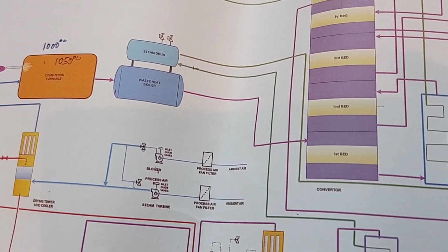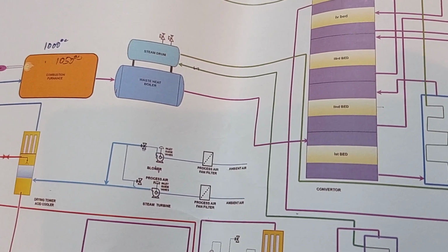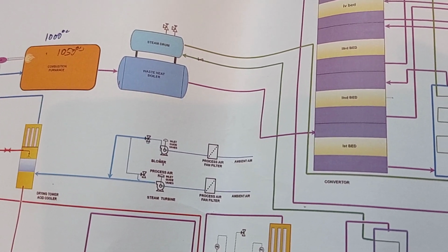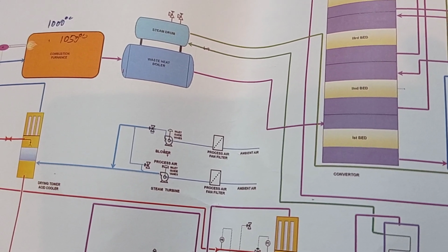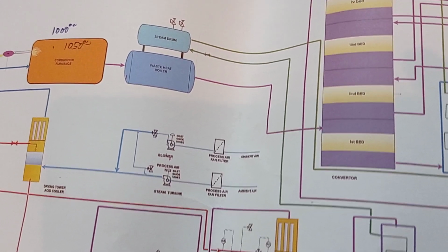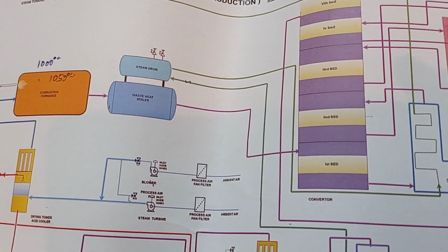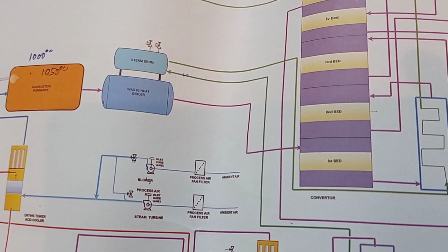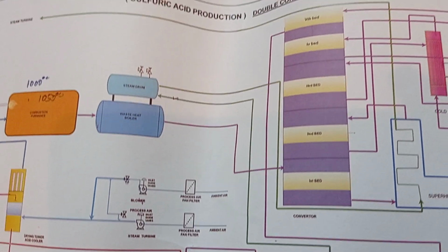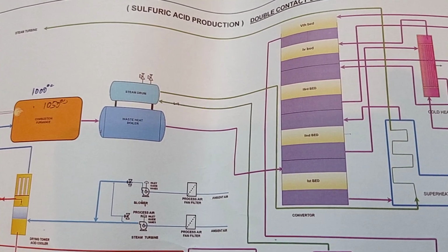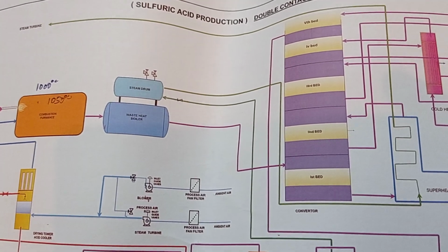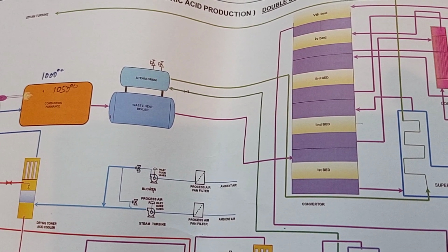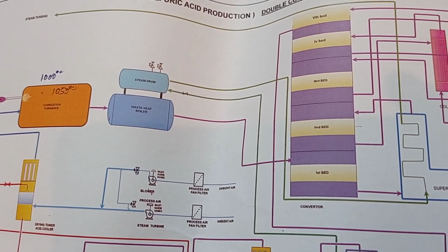So the temperature in operating conditions always depends upon the amount of catalyst you add. All these things are calculated as per plant cost, plant design and plant space. Everything is designed according to the catalyst, the raw material and our production rate. Based on those calculations we decide the amount of catalyst in the different beds, and that also decides how many beds we need.